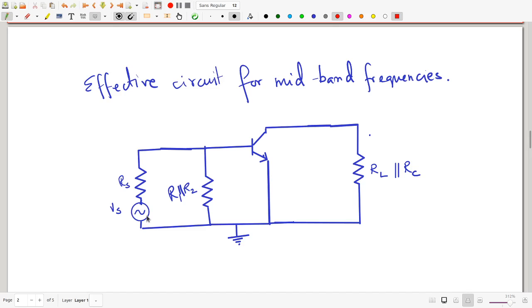And what will that do? These capacitances are actually pretty tiny, which is why you can actually ignore them. Notice that these capacitors, for example, the capacitor which you have in the base emitter junction would effectively be connected between the base and the emitter across the base emitter junction. So what would it do? If it carried current, it would actually divert current away from the actual transistor. It will just reduce the effect of the transistor itself.